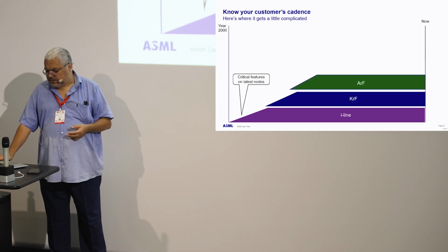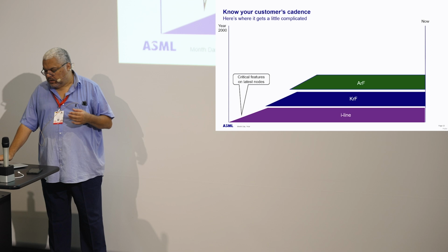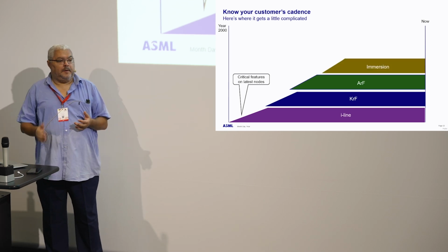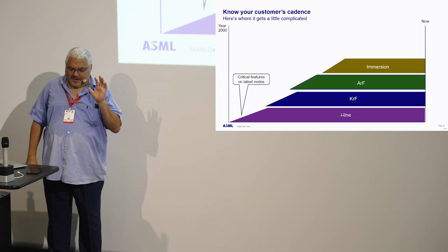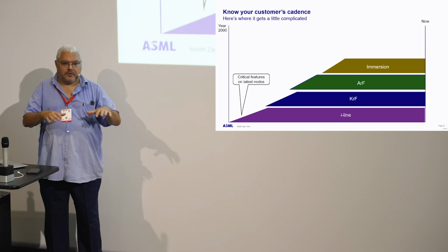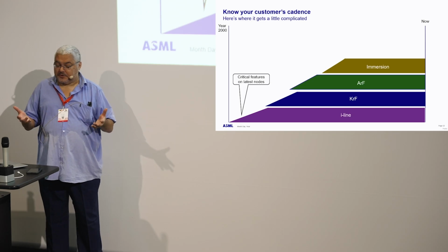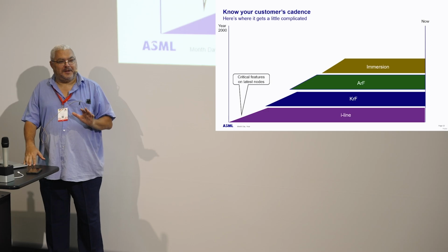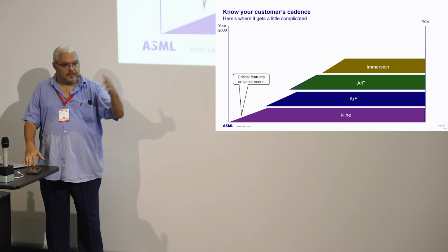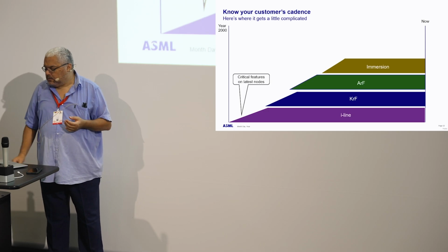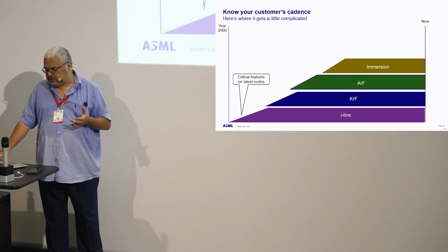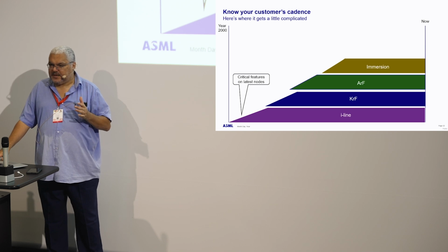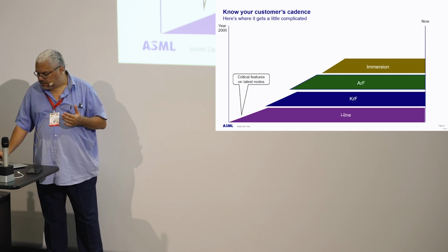And then the same happened with the introduction of argon fluoride immersion, which was a crazy moment when someone thought, oh, we can improve the resolution we can get by pouring water over everything while making microchips. It sounds a bit crazy, but it works, and gave an increase of numerical aperture effectively. And so this was maybe about 15-ish years ago that we were really working with immersion.